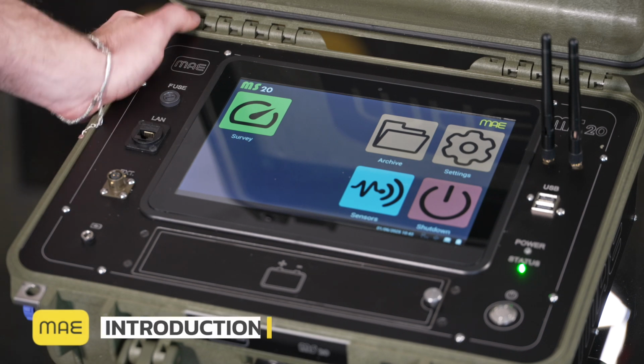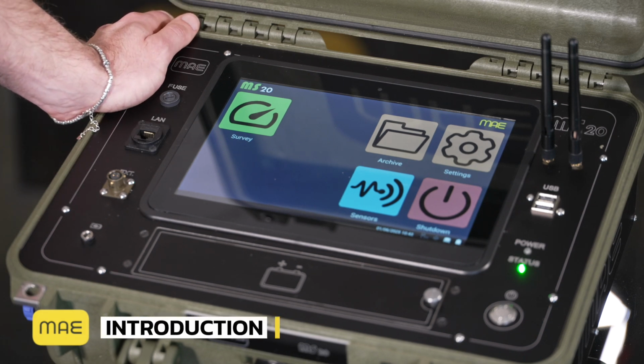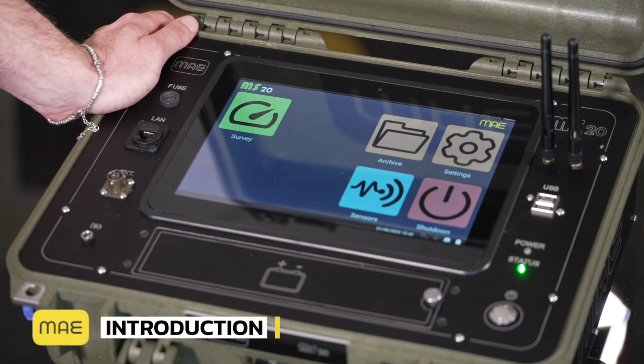Today we're going to talk about our solution for static load testing. The instrument is available in 10 or 20 channels. Each channel is independent. It's possible to use many kinds of sensors, from analog signal, both single-ended and differential, up to 10 volt, current loop for 20 mA sensor, load cells, or temperature probes.